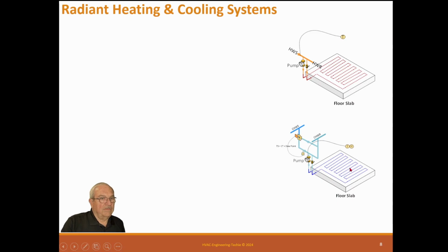And then you can have radiant cooling also. You could use the same tubes, but unfortunately we don't normally do that, because for radiant cooling we have to keep the water 1 degree above dew point so we don't condense on the slab. And these are also popular to put in ceilings. We don't want raining, so we put a temperature control loop in the chill water so that this is maintained 1 degree above dew point.